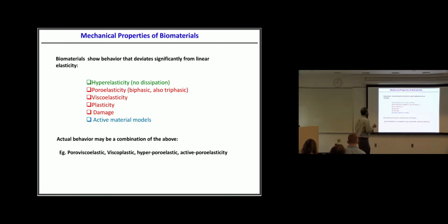So in a sense, this is like a linear elastic material, but it is non-linear, and there's no dissipation, meaning you keep pulling the material, taking the load out, and you will basically go back and forth without any dissipation. All the other models that I'm going to talk about have dissipation in them, and almost any material is dissipative for various reasons, and we'll see what some of these reasons are. Of course, you know from common knowledge that there is dissipation almost everywhere.